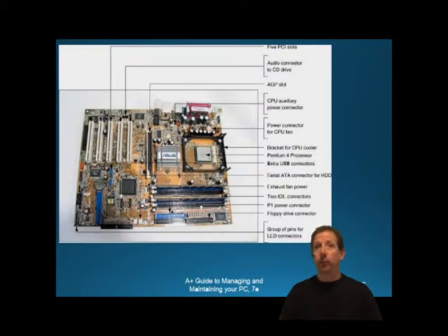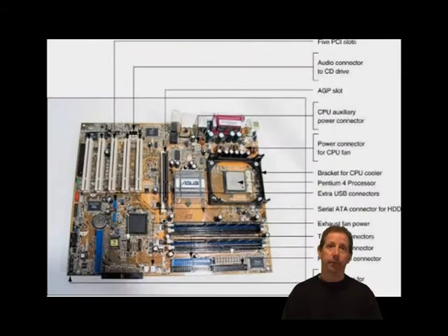Using a matching form factor for the motherboard, power supply, and case ensures that the motherboard fits in the case, that the power supply cords of the motherboard provide the correct voltage, and the connectors match the connections on the board, that the holes in the motherboard align with the holes in the case for anchoring the board to the case itself. The holes in the case align with ports coming off the motherboard.